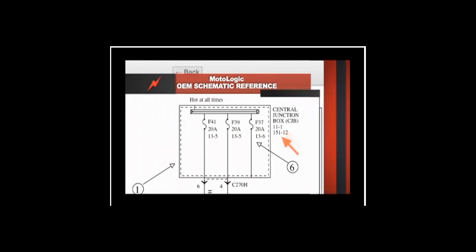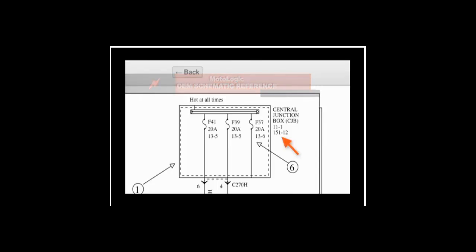Third, the internal name and function ID. Shown there, you're at the central junction box, which is labeled CJB, and Ford calls that 11-1. So it represents a specific point in the car, 11, and you're at the first terminal. 151.12 is a section on the car where that typically could be found.